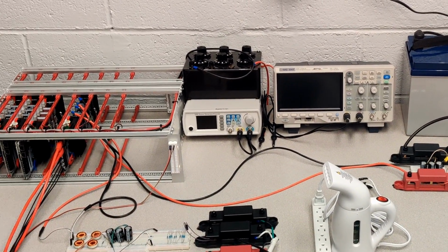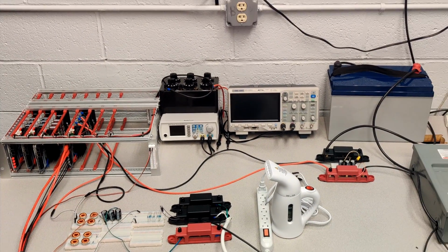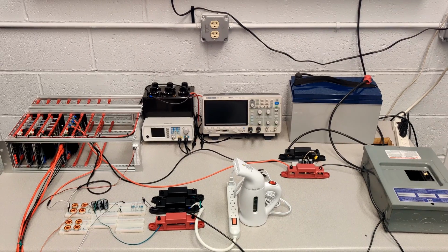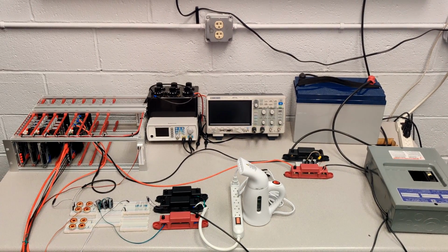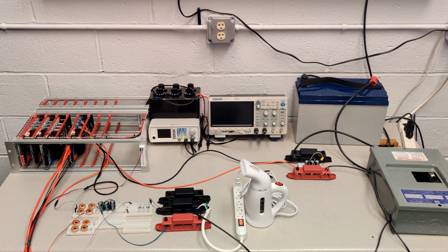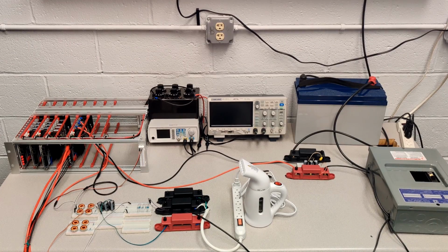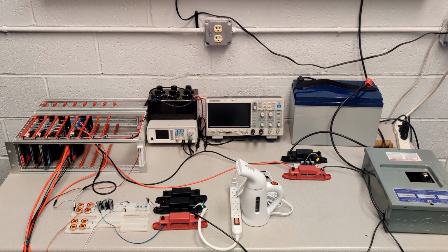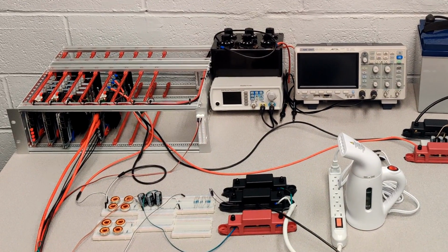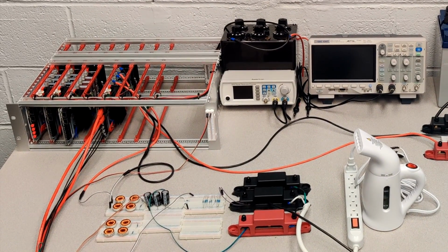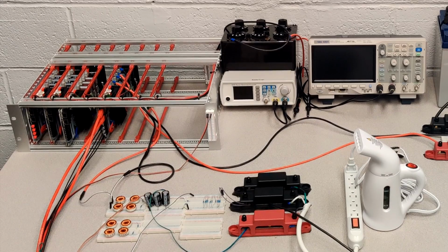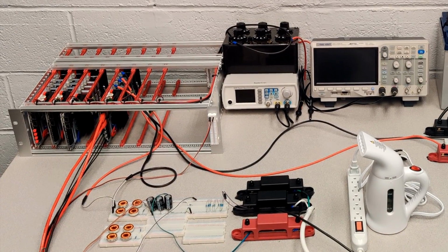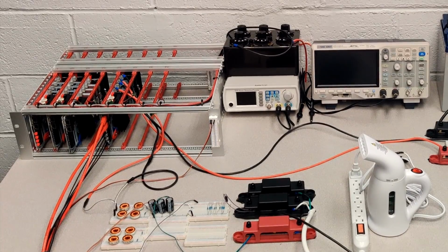And an H bridge connected to the voltage source is expected to form a voltage source-based inverter. To achieve this, PWM signals from the controllers drive the H bridge, converting the DC voltage to AC voltage. Then, a parameterized LC filter smooths the AC power before it is injected into the AC bus. And so the AC bus can power the load, for example, a water boiler here.